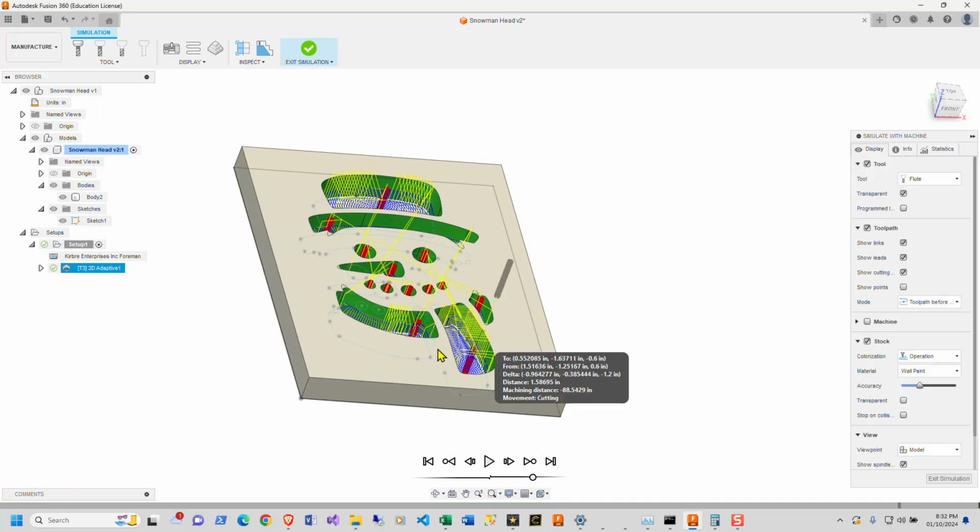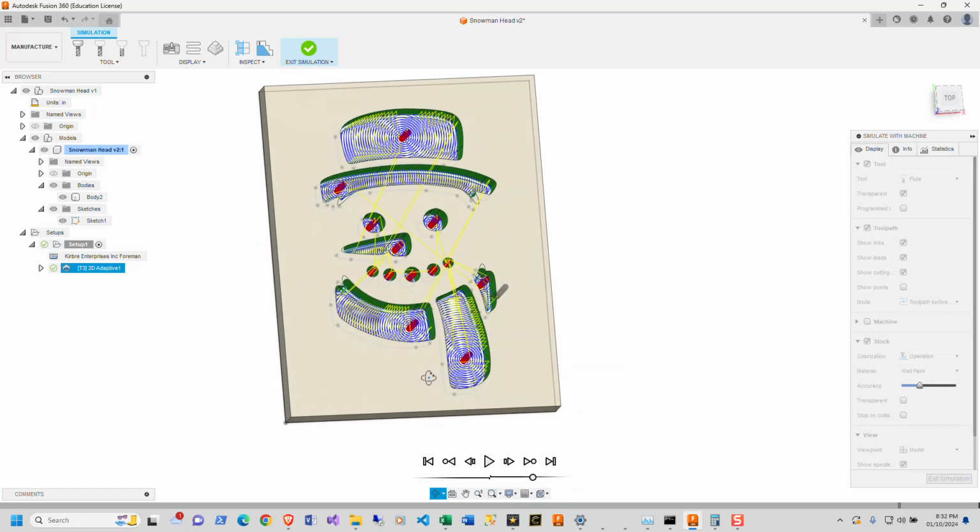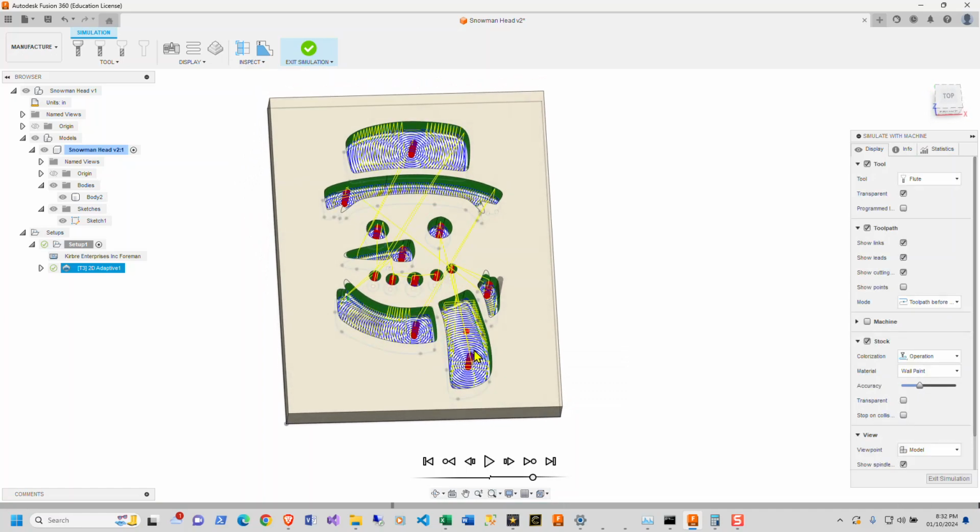Now, something is a little unique with this. If you're new to Fusion 360, this guy does a circle, does a spiral, and does always this climb cutting. So you're not having this thing run back and forth like this, bang, bang, bang. Your machine won't bang around anymore.